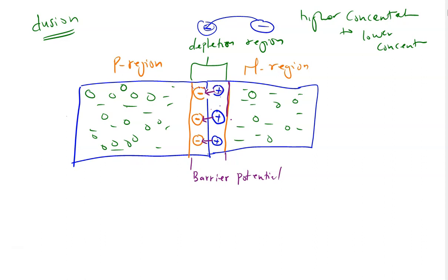The same way, once the electrons move, it will get to a point and the equilibrium will be obtained, and the electrons here cannot move again because we've created a depletion region, right? And in that depletion region, there's a potential barrier or barrier potential existing between it, and this is more like Coulomb force. Okay. So it's existing between it, and it is preventing this electron from moving, right?